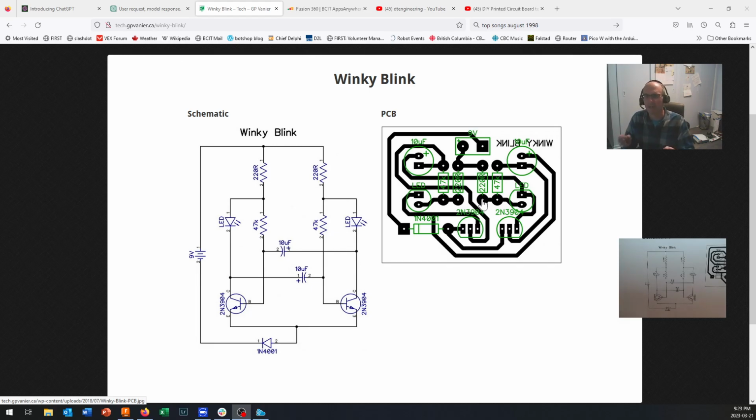And the key part about it is that you're going to have two holes on the printed circuit board that you're going to drill through the circuit board so you can fit the leads for that resistor through there. And there's going to be two pieces of copper right there that are going to join together. And those pieces of copper aren't going to touch anything else on the circuit unless this schematic diagram says that they're supposed to contact, because on this schematic diagram you can see right here that this side of this resistor connects to this resistor and to the LED. So if we take a look over here, we'll see that our 220 ohm resistor comes out here and it connects to a 47 K ohm resistor, and then it comes over here and it connects to the positive side, the anode of the LED.